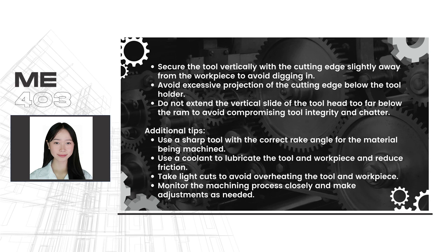For additional tips, use a sharp tool with the correct rake angle for the material being machined. Use a coolant to lubricate the tool and workpiece and reduce friction. Take light cuts to avoid overheating the tool and workpiece. Monitor the machining process closely and make adjustments as needed.